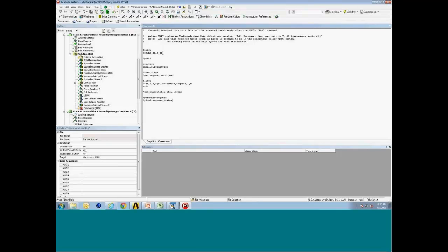We're going to resume the analysis database, which includes the name selections. And I'm going to select my local nodes name selection. We know those are nodes. I'm going to sort to get the maximum stress on those nodes. And then maybe I need the number of elements within 90% or greater of that maximum stress value. If I have some kind of post-processing routine that needs that number, I can get the number of elements count within 90%. Once you insert the command block, this will be executed just after /POST1.